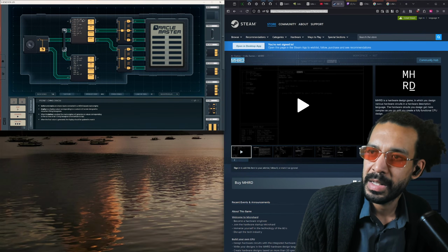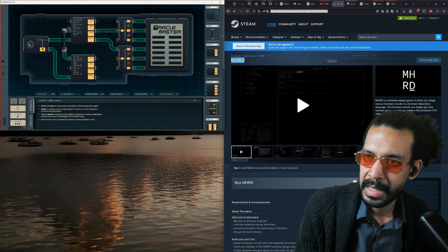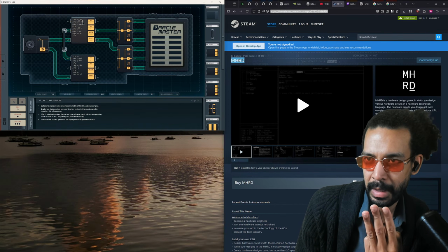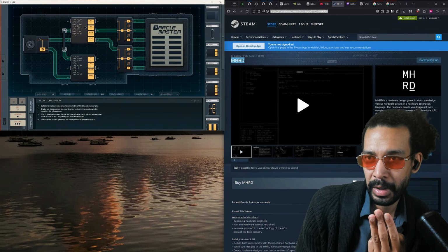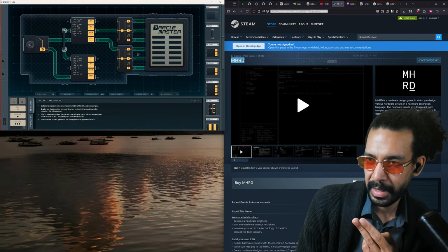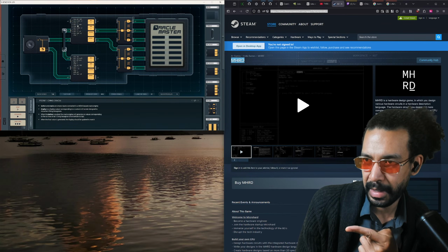So this control module waits for a button press. Once it sees a button press, it asks this for 3 bits to turn into one 3-digit number. And it asks it to do that twice. Then once it has both those numbers, it sends one to this multiplexer and sends another one to this multiplexer.